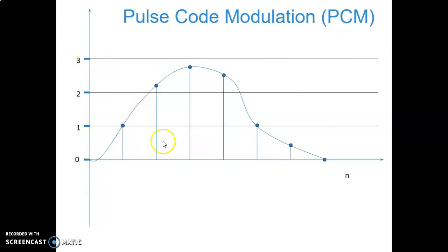These are the 4 levels of quantization, and this is what quantization is: assigning nearby values to a particular sample. Between 0 and this particular sample, there is no sample at all, so 0 will be assigned to this level. You can see this red line. Now there is one sample having an amplitude of 1 volt, so this sample will be assigned 1 volt as a quantization level. Then holding: once it is sampled, it will be held at this particular level.